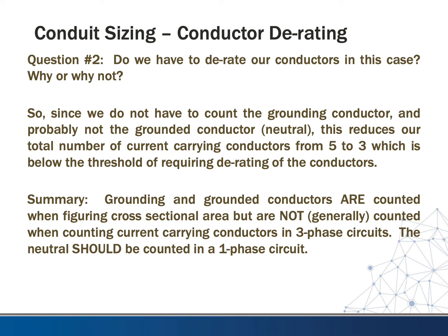So one interesting case that pops up many times, though, is modular furniture. Modular furniture usually can come in 3-circuit, but it also comes in 4-circuit furniture, so you have to supply 4 circuits to it. Many times, depending on how you're going to run your conductors to this location, it could require you to derate your conductors, which oftentimes we have to.